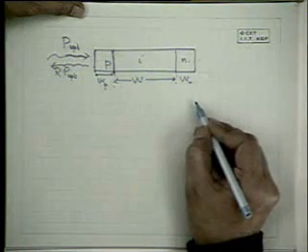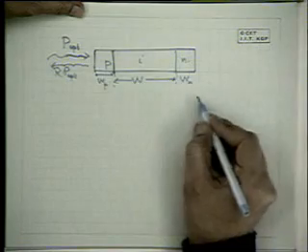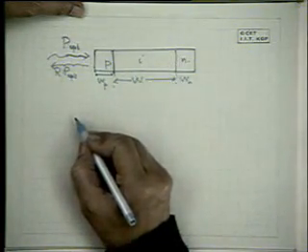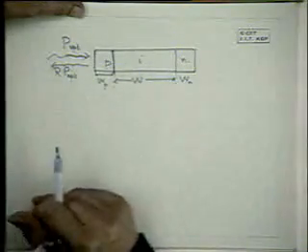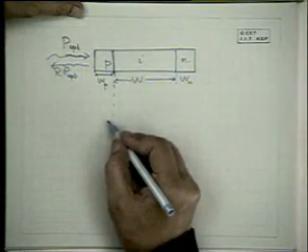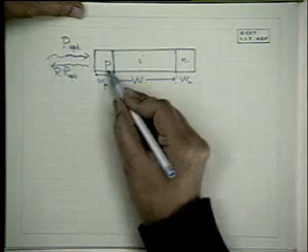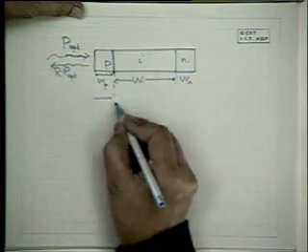We want to have depletion layer conditions, so this I region should be depleted of carriers, so that any carriers created by the light should be detected and separated very fast. So we have reverse bias, N positive, P negative, and as a result the band diagram will be something like this.